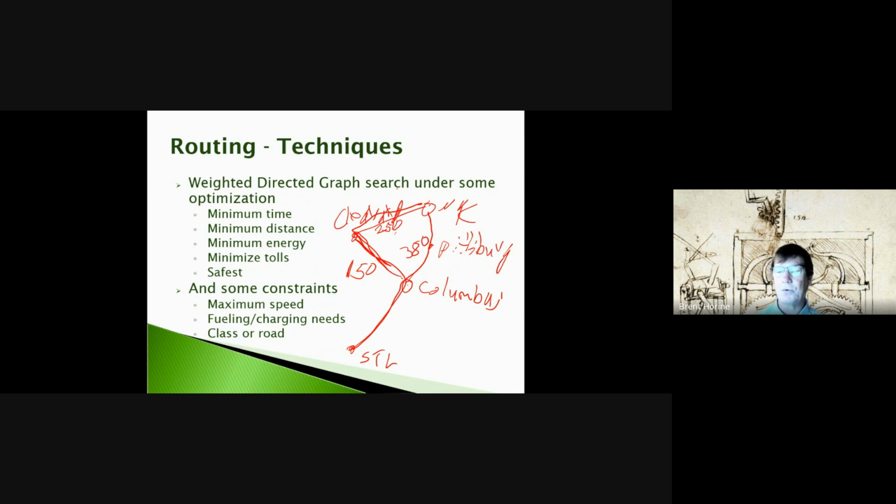You might have to wait for pedestrians to clear or that type of thing, right? And left-hand turns might have an even higher weight because you might have to wait for traffic and pedestrians, right? Generally left-hand turns are a little bit more risky type of movement. So your book talks about assigning weights in those different ways, and so maybe if you can find a route that favors right-hand turns versus left-hand turns, you're going to be better off, right?